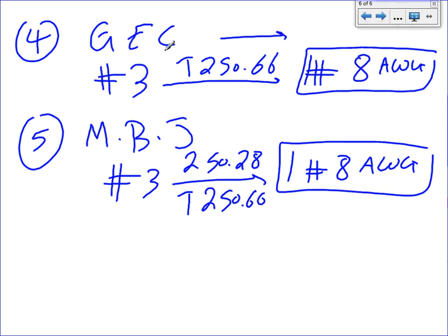Every welding shop has lights. If I have a service panel feeding the welders, where are you going to feed the lights from? Most likely from the same panel, if it's a small shop. So you add the lights, the receptacles, and the HVAC equipment for heating and cooling, exactly like we did the welding load, and size your panel.